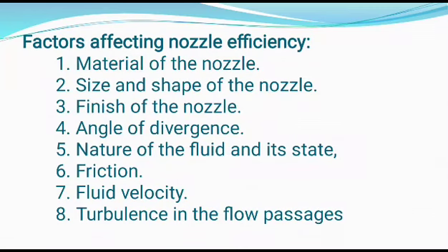There are 8 factors. First one is the material of the nozzle. Second is the size and shape of the nozzle. And the third one is finish of the nozzle. And the fourth one is the angle of divergency. And the fifth one is the nature of fluid and its state. Sixth one is the friction. And seventh one is the fluid velocity. And eighth one is the turbulence in flow passages.